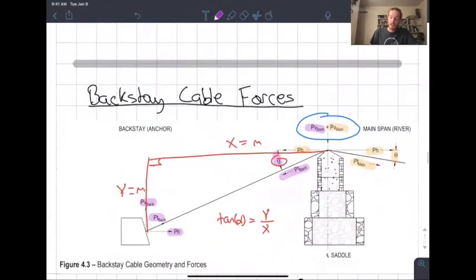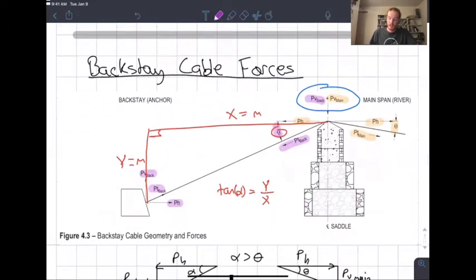So if you were thinking alpha, you're right. If we really lowered alpha, say we dropped our anchor and we just made a super steep anchor right here, that would really change what this tower reaction is. And depending upon all the geometry and the numbers, if you had a super steep alpha, you might be able to get to the point where your low side tower reaction is actually higher than your high side. Typically, we wouldn't want to design something like this, but I just want you to go through that process of thinking about what can be changed.